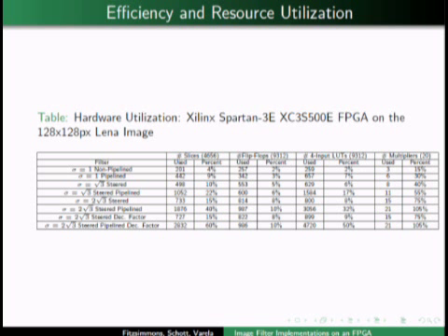But it's not as evident in these ones, but as you get to needing bigger masks or FIFOs to store the data, you can see that's like a 4 times increase in resources for the pipelined implementation. And additionally, in the pipelined implementation, you need to use more multipliers at once because you're not doing one convolution and then reusing the multipliers. You're using all of the multiplications at once.